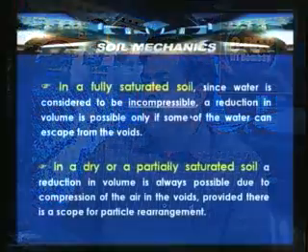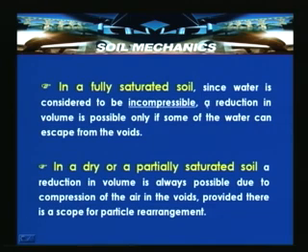So, in a fully saturated soil, since water is considered to be incompressible, a reduction in volume is possible only if some water can drain out of the soil. That means that in a fully saturated soil, a reduction in the volume is possible only if some of the water can escape from the voids. So, any reduction in the volume is expected only when water starts draining out of the soil.